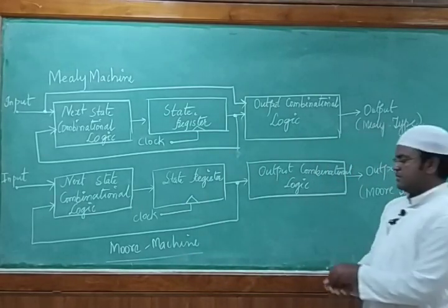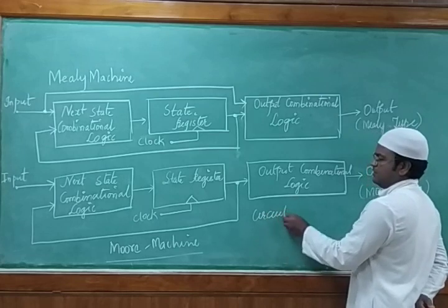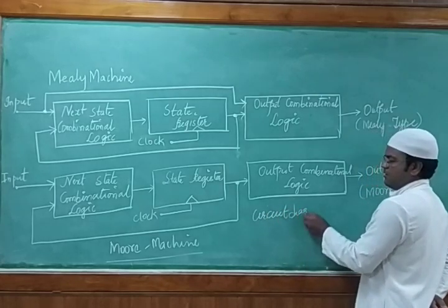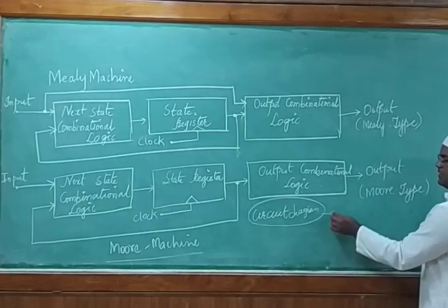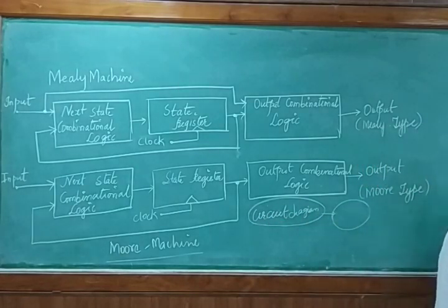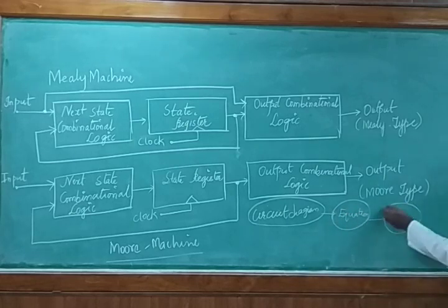Basically, to get the state diagram and state table, first you should have the circuit diagram. After getting the circuit diagram, you pass it to the equations, meaning using K-map or any kind of functions, you develop the equation. Then we need to prepare the state table. After getting the state table, we have to write the state diagram.